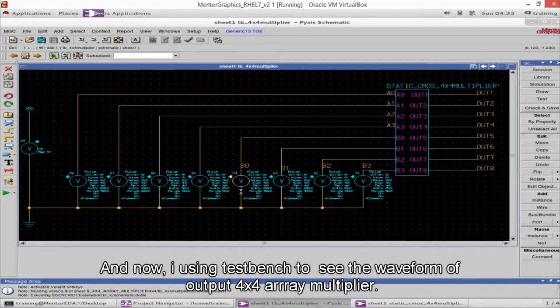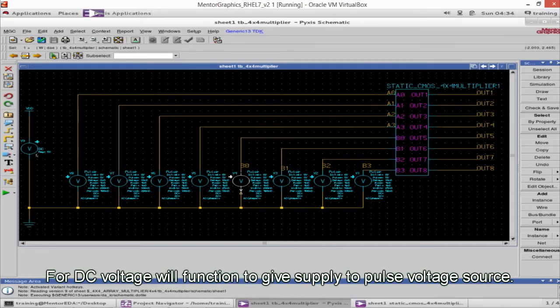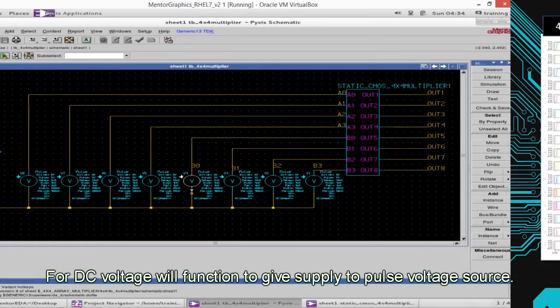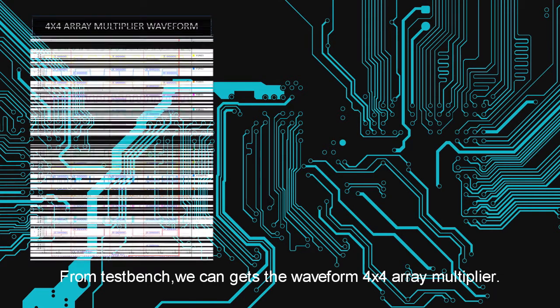And now, I'm using testbed to see the waveform of output 4x4 array multiplier. When to insert the input, I'm using pulse voltage source to apply input waveform. For DC voltage, will function to give supply to pulse voltage source. From testbed, we can get the waveform 4x4 array multiplier.